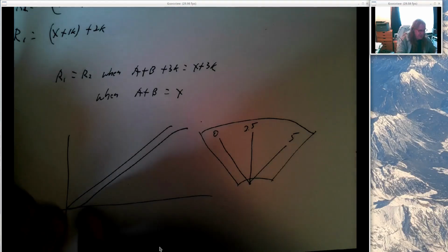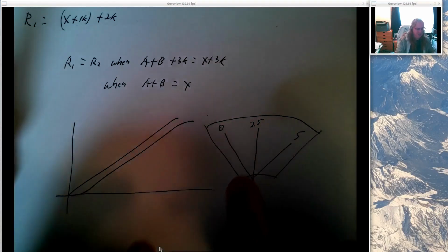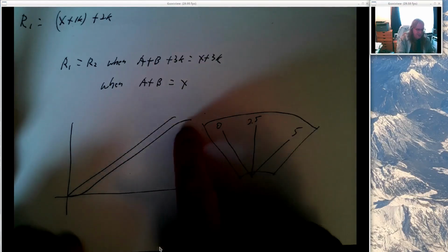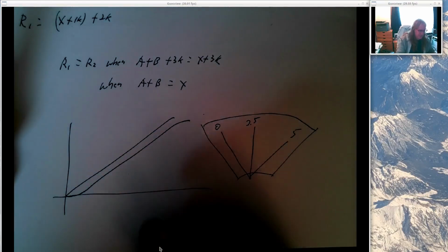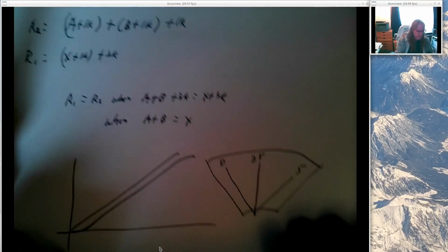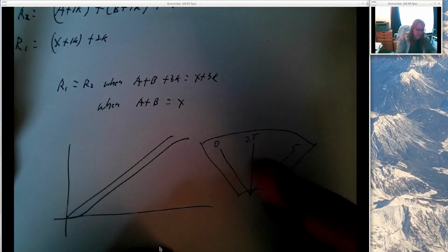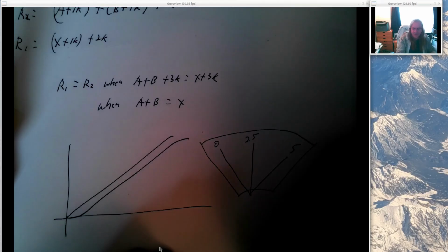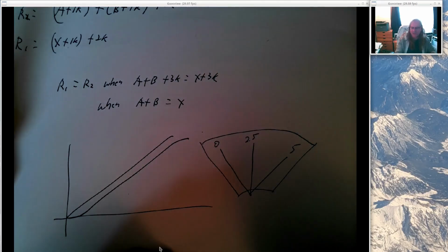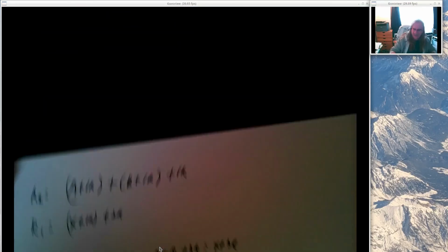And so in the beginning, when you first start turning it, and at the end, when you're close to the end, the change in resistance is much flatter. But it's linear in the middle, say 80 or 90%. So I decided, instead of going from 0 degrees to all the way turned, I would ignore the first 10% or so of the rotation, and I would ignore the last 10% or so.